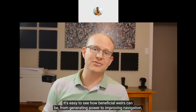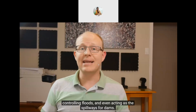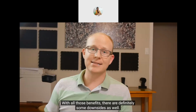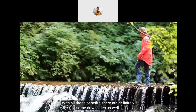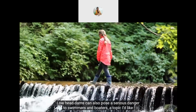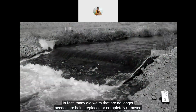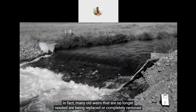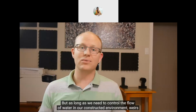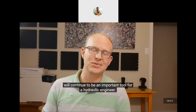It's easy to see how beneficial weirs can be, from generating power to improving navigation, controlling flooding, and even acting as the spillways of dams. But with all those benefits, there are some downsides as well. Impoundments across rivers affect the aquatic environment. Low-head dams can also pose a serious danger to swimmers and boaters, a topic I'd like to discuss in the future. In fact, many old weirs that are no longer needed are being replaced or completely removed to restore the river to its natural state. But as long as we need to control the flow of water in our constructed environment, weirs will continue to be an important tool for a hydraulic engineer.